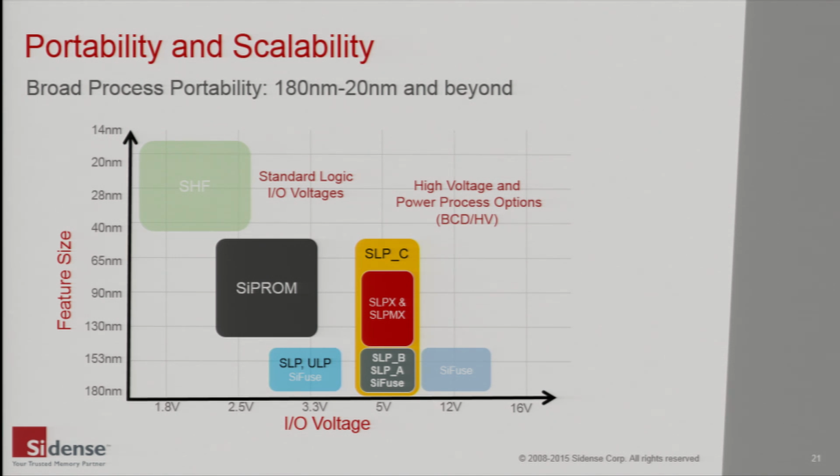Portability and scalability. The universal acceptance of Sidense OTP makes for quite a challenge, particularly for us guys at Sidense. The diverse range of chips with many different requirements, from high performance logic through precision analog to BCD, means that the Sidense OTP has to be qualified in a wide range of nodes and voltage variations. Furthermore, this OTP needs to be available in a wide range of foundries and also IDM processes.